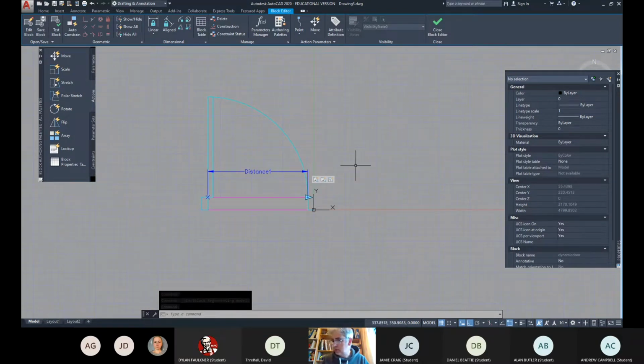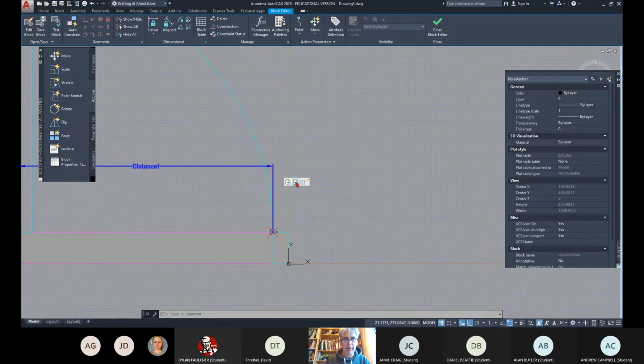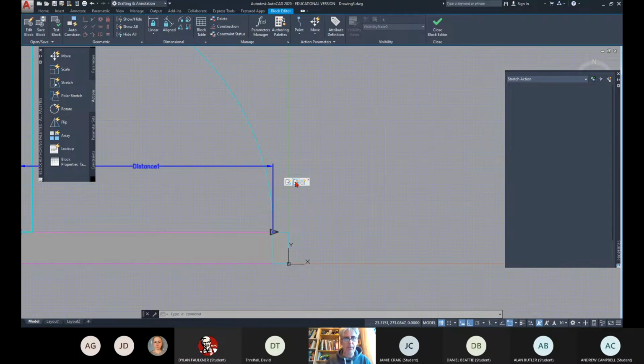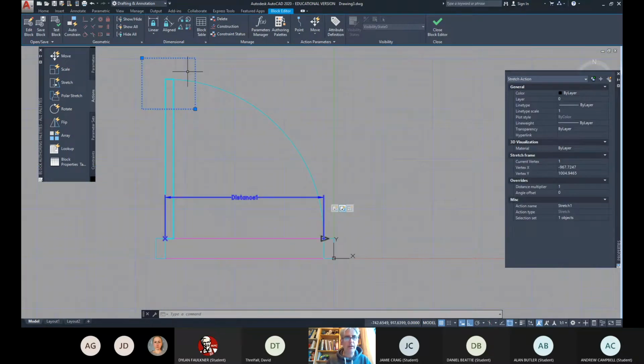Now what we want to do is click on the second stretch symbol, right? This one here. You should see a stretch one, but if you've renamed these, it'll probably be stretch 2. So it's the second one that you did. If you click on that, you'll see that the dashed box appears up here where you did the selection box. Go across to your properties box.